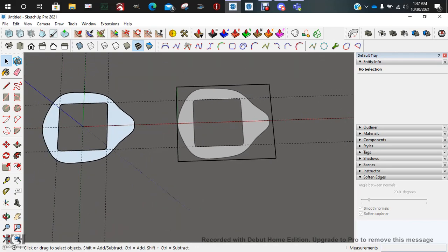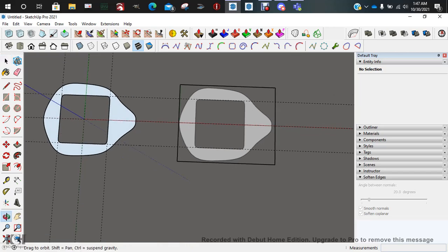Now you're probably wondering, why is it 40 meters and not millimeters? That's because in millimeters, when you start modeling, especially with lofts, you get such small faces on some of the geometry that they interact with each other and delete each other, overlap, and it causes issues. So I scale it 1,000 times larger and then scale it down at the end. And that's just a rule of thumb that I've always done.